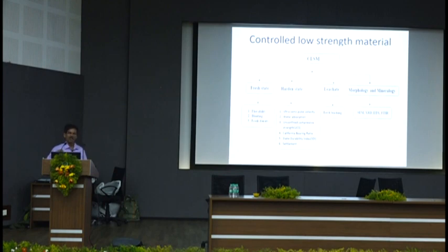It was interesting to see in Hong Kong, it is written there. Initially it was 4-storied, then they made it 16-storied, and now it has come up to some 70 stories. But the place is the same, so they have to go only vertically up. So that's why, during one construction of a canal, they were not allowed to dump the material anywhere. So they have to use that material nearby. That is how this material called controlled low strength material came about.